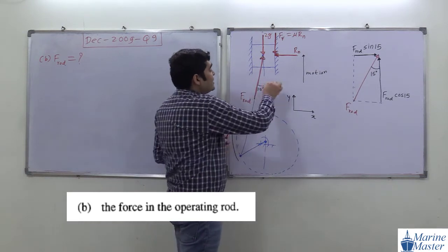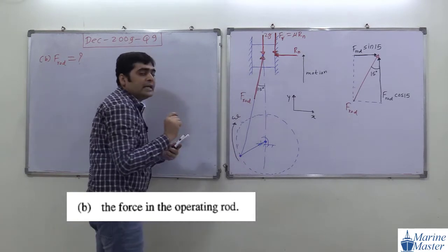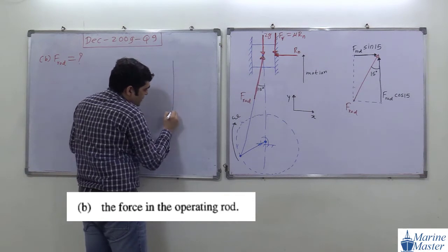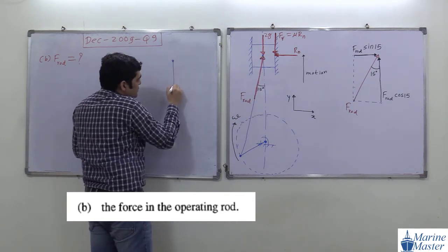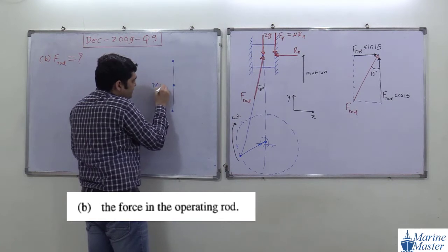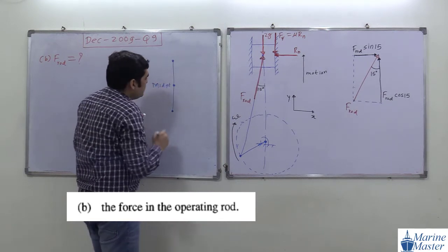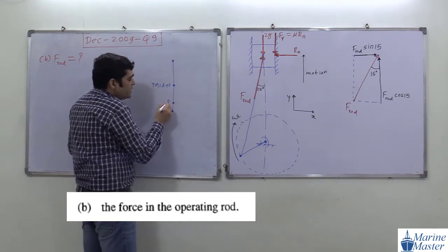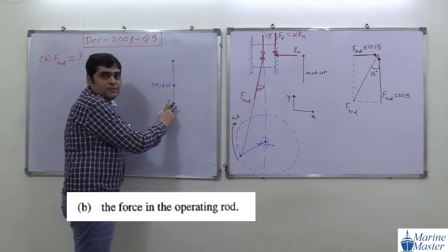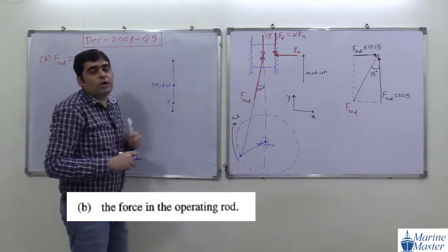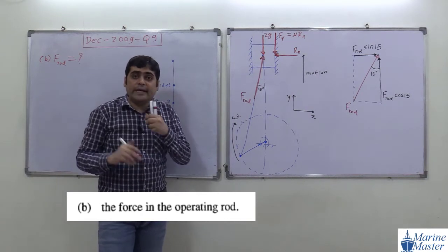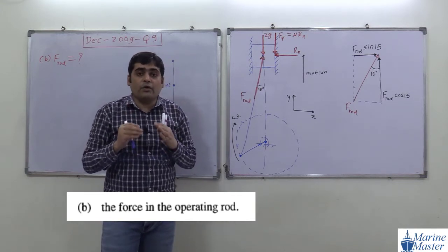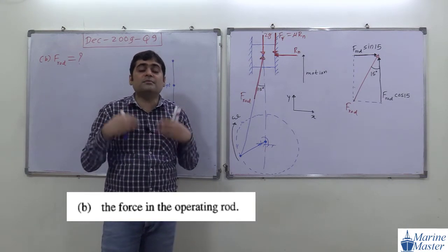Now there is an acceleration in the y direction. In which direction is the acceleration? Okay, I have erased that drawing, but try to see the point here. This is our midpoint, and this is our point P, the position of the block. With respect to the block, where is our midpoint or mid-stroke? It is above. And we discussed that acceleration is always directed towards the mid-stroke or fixed point.